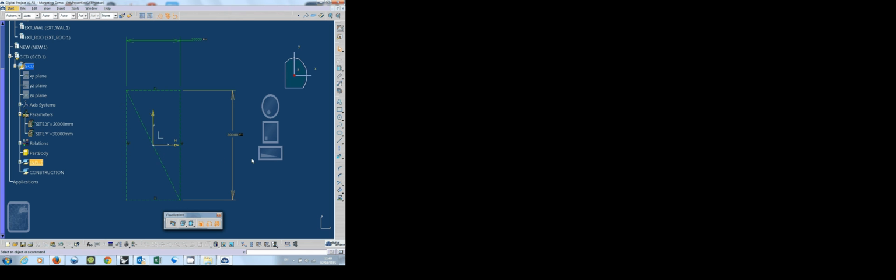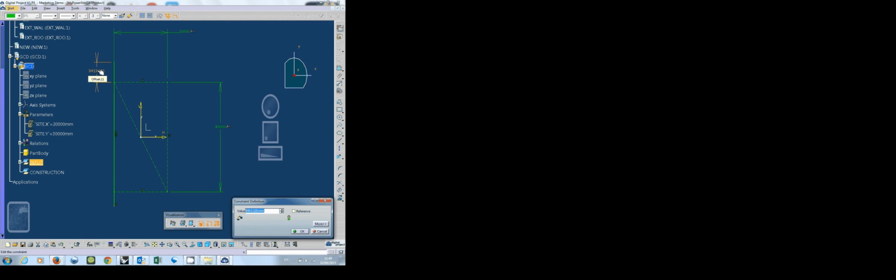So from there, I draw just one line, such that the end of the line always keeps 3 meters away from my boundary. This will serve as the first grid line.